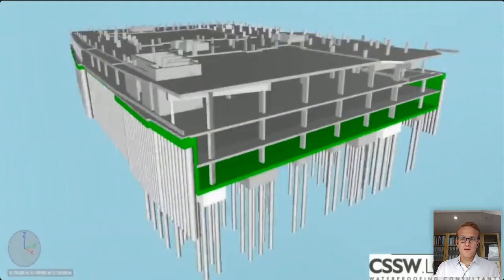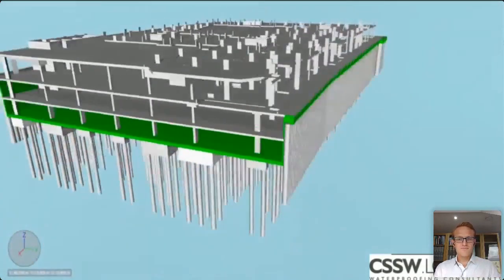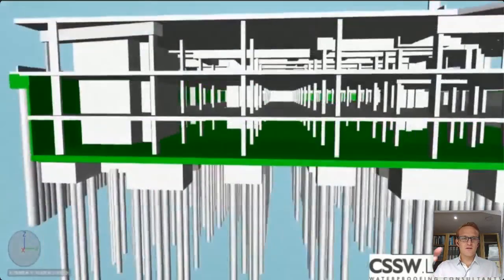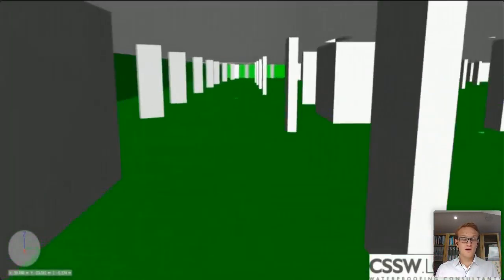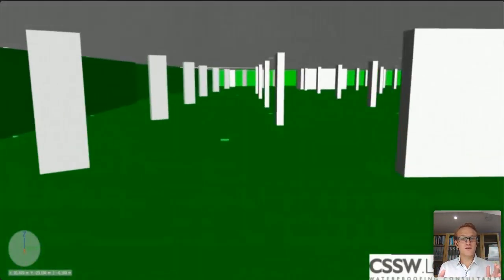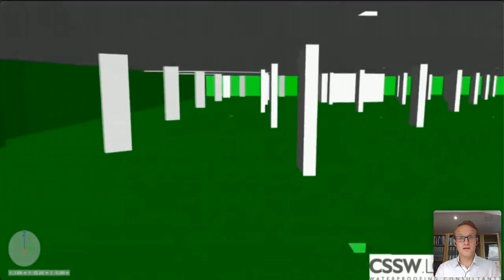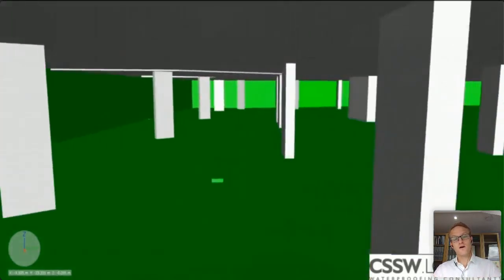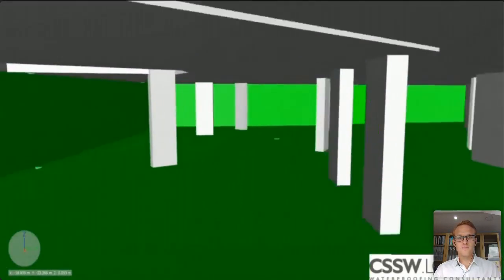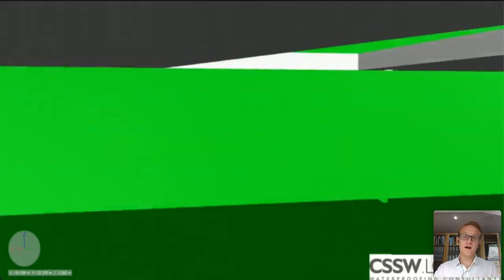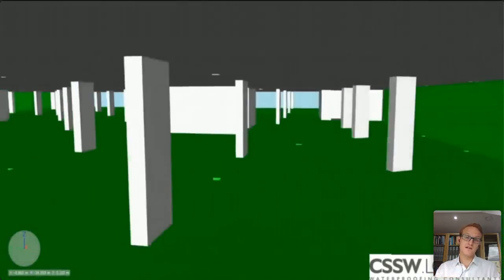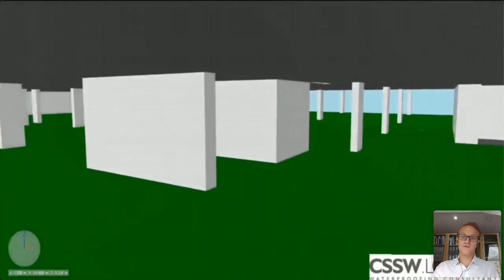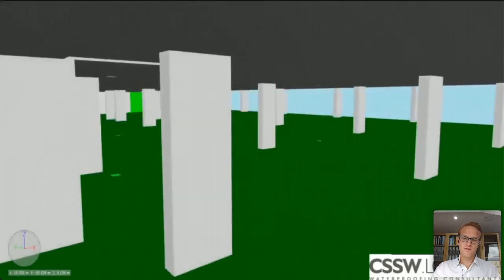And this is just a 3D thing that gives you an idea of scale, green being the watertight concrete. So on this sort of scale of project, if you can lose 100 mil off your concrete section, you use a lot less concrete. The embodied carbon for that building goes down significantly. But the way we had to do that was A, working very hard on the crack widths, and B, using a waterproofing additive, because we couldn't quite go as far down as 0.06 millimeter crack width.